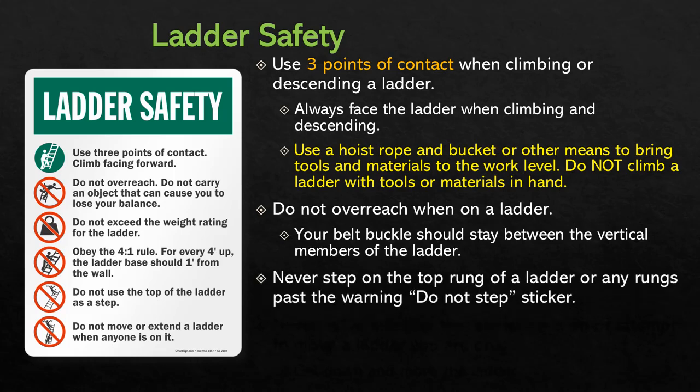Never step on the top rung of a ladder, or really any rungs that have a do not step warning sticker on them, as you will often see on the highest or even second to highest step on an A-frame ladder. When you step on the high rungs of a ladder, it's an inherently unstable situation, and you're greatly increasing your chances that you're going to accidentally kick the ladder out, and therefore you're going to fall.